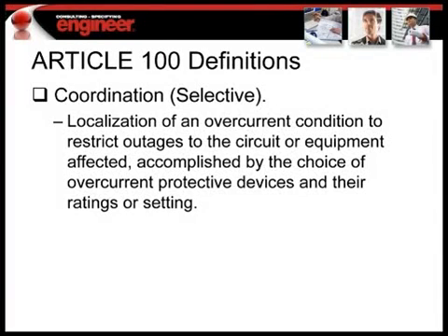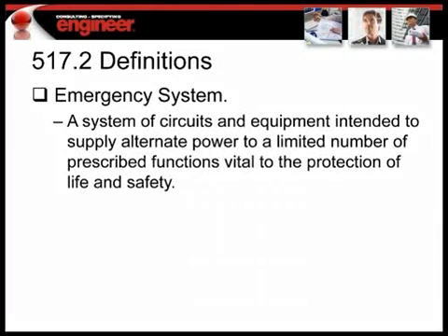Okay, Jim already covered coordination, so basically this section of the code defines what selective coordination means, and this section here tells us that the emergency systems have to be coordinated. This particular article is found in 517, which is in the healthcare section of the National Electrical Code.